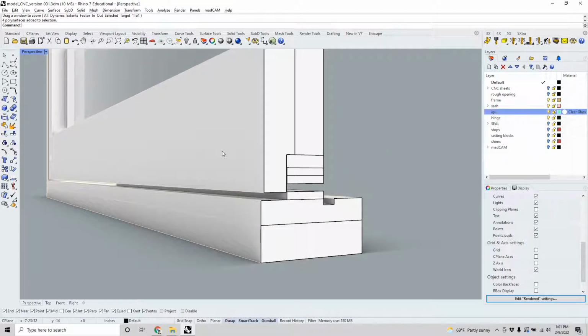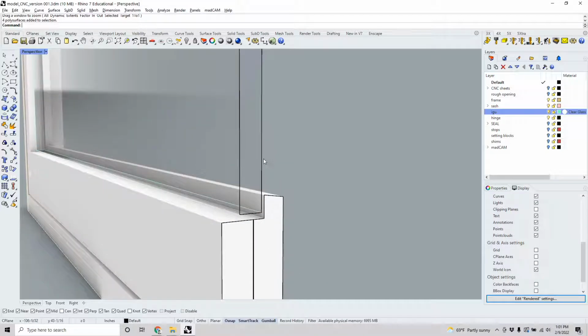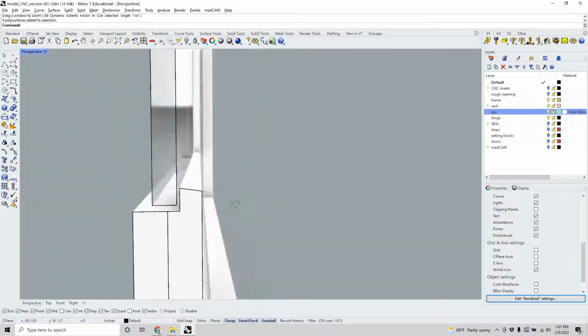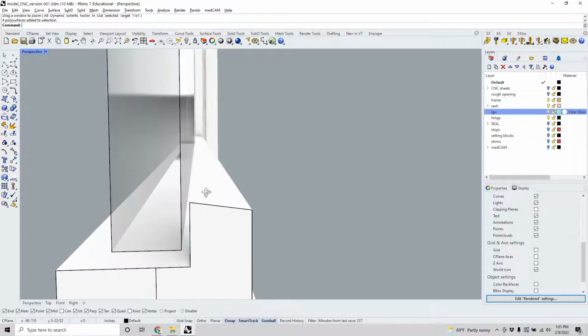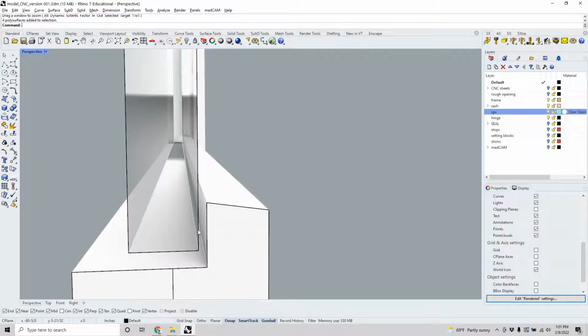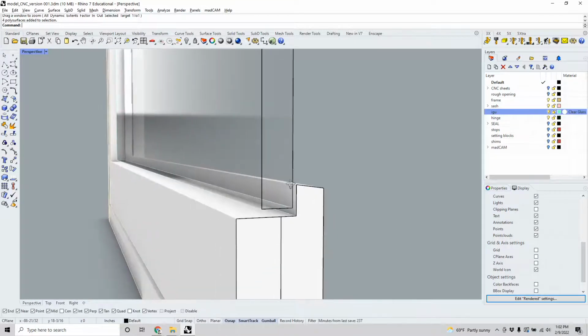All right, so in terms of the glass, here is the sash, the IGU, the insulated glazing unit that sits in the sash, up against the rebate. Now there's a little gap here, right there. That's 1/16 of an inch, and that's meant to accommodate the glazing tape, which is a double-sided tape that seals the glass against the sash and seals out the weather.